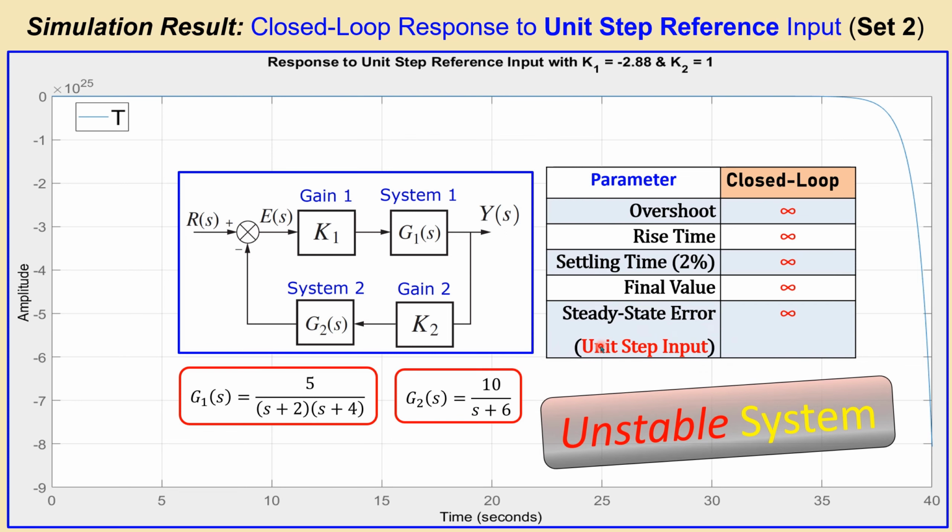And I cannot use this because I said in my discussion that stability is mandatory to be able to do the steady state error calculations. The steady state error formula gave us these two values, so that was actually valid according to that formula, but the stability check is actually showing us that this is not a valid solution.